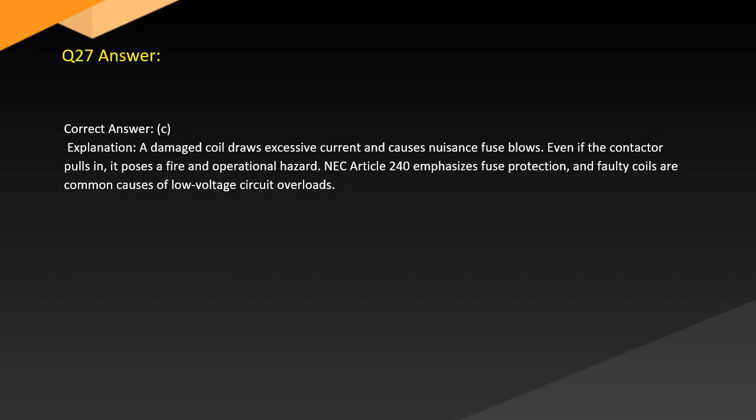Answer. Correct answer: C. Explanation: A damaged coil draws excessive current and causes nuisance fuse blows. Even if the contactor pulls in, it poses a fire and operational hazard. NEC Article 240 emphasizes fuse protection, and faulty coils are common causes of low-voltage circuit overloads.